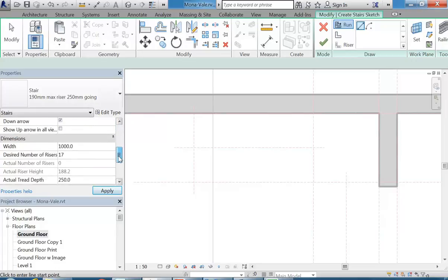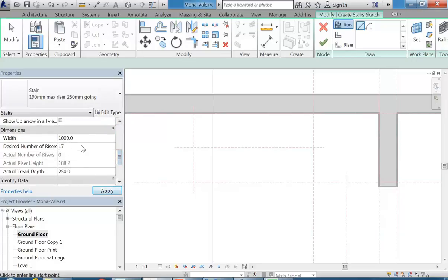Okay, so it's just like the design process you probably follow whenever you're designing a stair. You begin by working out where the stair is going to begin, what level the stair is going to begin on, and what level you're trying to get to. That's always the starting point, or if it's not, that's the way you're supposed to do it.